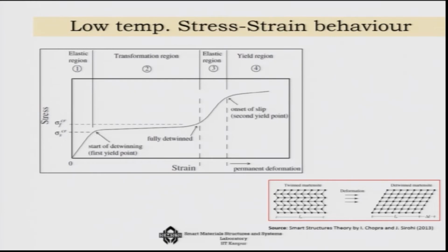It is because even though it goes from BCC to FCC, the crystals very nicely create a fold. You can see a fold here, a fold here, a fold here. These folds take care of the expansion or contractions that could have happened in the system. That is why there is no shape change that you will see if you cool a system from the austenite phase to the martensite phase, and this particular martensite phase is called the twinned martensite phase.